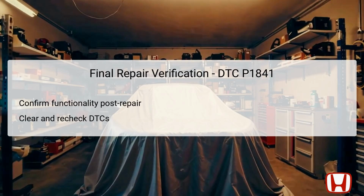This verification process validates that the repairs made effectively addressed the underlying issues with the CVT speed sensor or TCM. Additionally, it's crucial to ensure that the transmission operates smoothly in all modes, particularly in reverse. Verifying these aspects ensures that the vehicle is restored to its optimal performance before returning it to the customer.